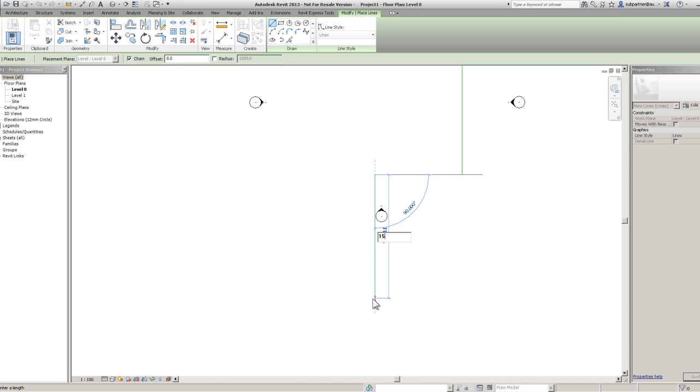And if I put an apostrophe afterwards, press enter, it will actually draw a line 15 foot, but it will do it in millimeters, okay? I know, it's a great little tool, okay? And let's just say we want to draw something across, and we know it's got to be 300 inches, the standard sign. Done. So I know 300 inches is basically 7,620 millimeters, and it just changes it automatically for you.